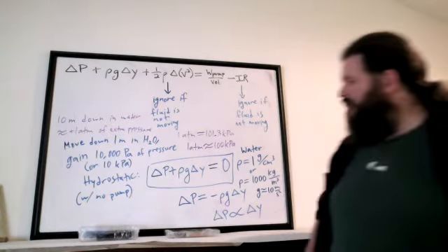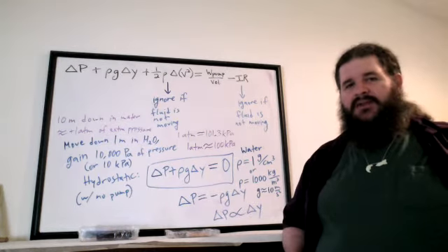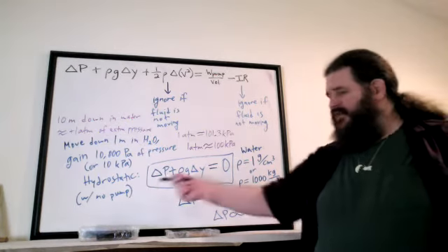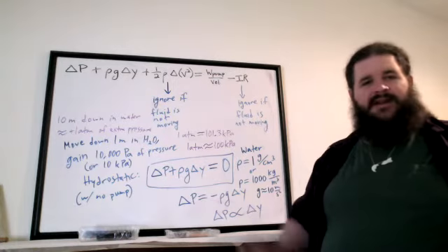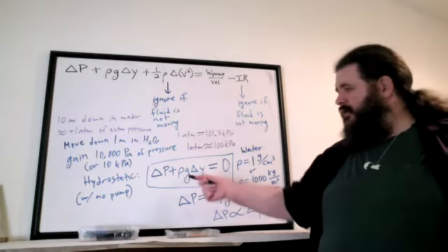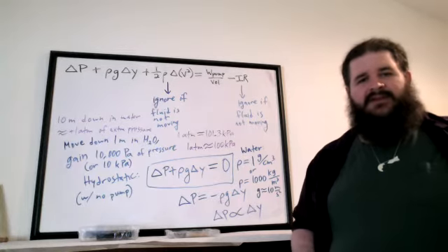And that general idea should be true in any hydrostatic system. Anytime you've got fluid that's not moving and there's no pump, it's going to behave exactly like this. Of course, if it's not water, you're going to be using a different value for density. And if it's not on Earth, you'd be using a different value for gravity. But the mathematical principle still applies even if the numbers are different.